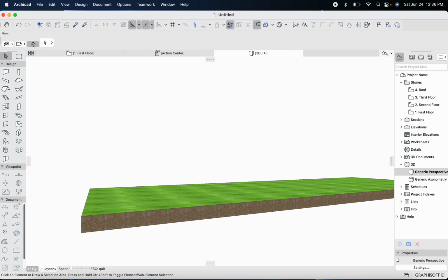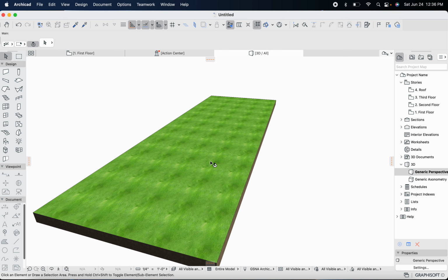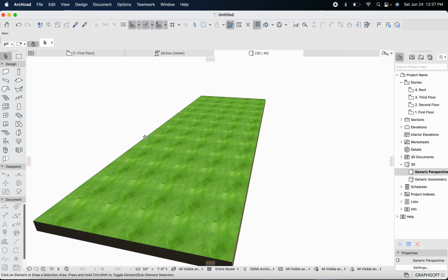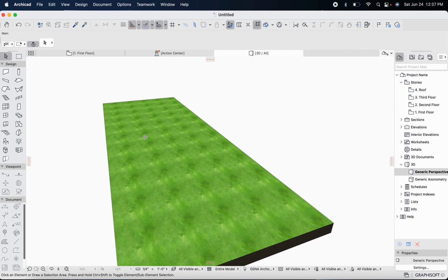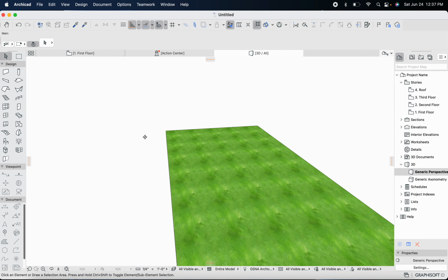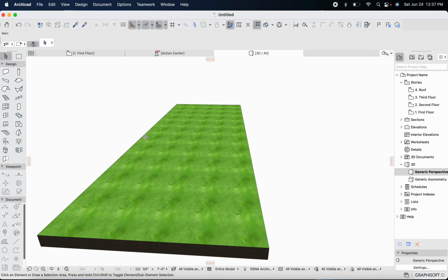Okay, and we can see that we've got our mesh there. Now I'll show you guys what I just did in order to move around the 3D model in just a second. But there's a couple things. For now, I'll just show you guys. You can use it if you hold down the Shift key while you're in 3D view, and then if you're on a Mac, you just use 2 fingers. You can sort of just slide around your model like so.